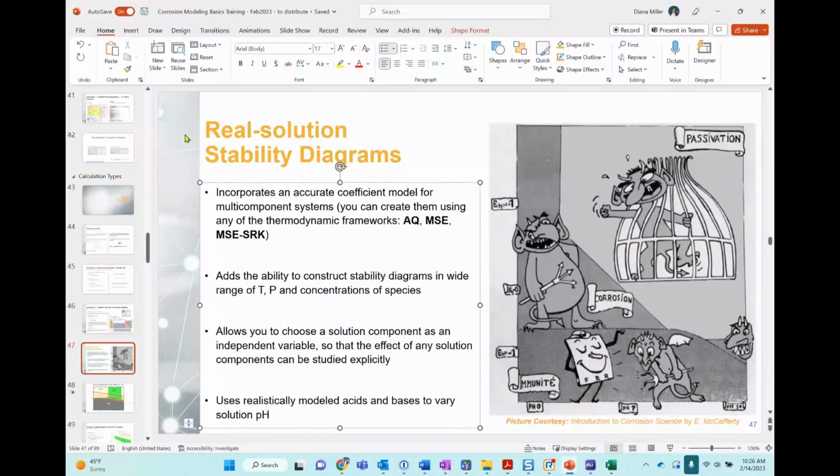So when Pourbaix created his atlas, if you're a metallurgist, you will know that it's all in pure water, right? Everything is done in pure water. And that's a good approximation, but in reality, we don't have pure water. We have ions dissolved in our water, and the ions or the salts make these solutions non-ideal. So then you have to incorporate this correction, which is the activity coefficient of the species. And we do just that. The software does those calculations for us.